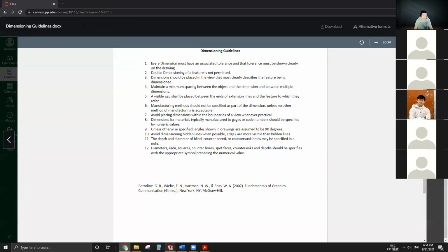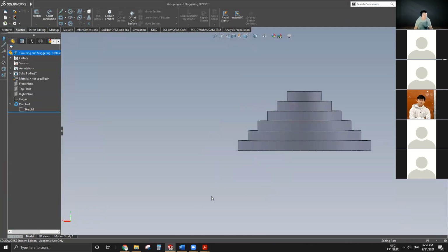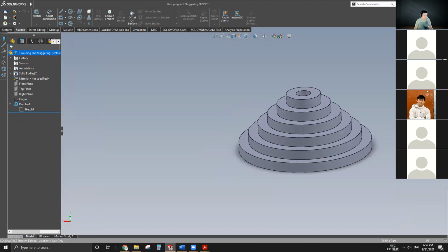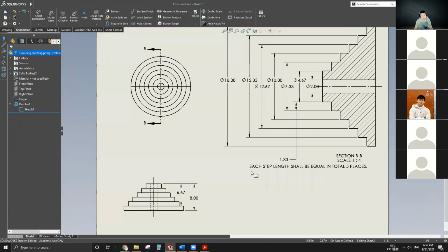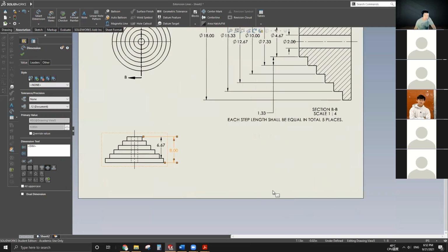The purpose of setting up a tolerance is that you want to control a certain feature, right? So let's say this value is regulated by default tolerance, which is plus minus 30 thou. Even though it doesn't say plus minus anything, your title block should have a default tolerance of plus minus 30 thou or so. So this distance could only be 8.03 or 7.97. That's a controlled distance.